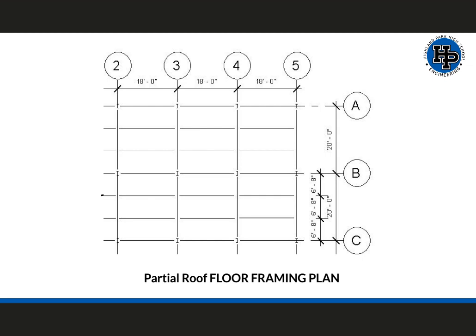There are a few things that you're going to want to be aware of. So these I's are the I-beams or columns in your floor framing plan. We also have these beams, which are these horizontal members here in red. We also know that the beam span, or the length of the beam, is 18 feet. We can see that specified here. And lastly, we also have these larger and longer beams, and we're actually going to refer to these as girders. These girders are 20 feet in length. This information is going to be super important as we move forward throughout this problem.